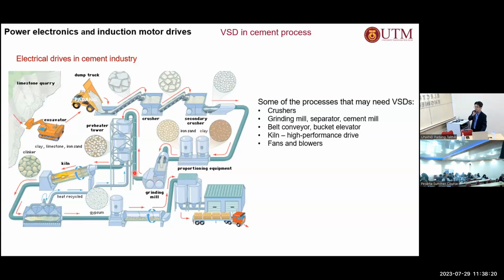And then of course, to transport everything from here, you have the conveyor belt, again using a drive. And if you use a belt conveyor, then you need to control the speed as well, because of the process flow, you probably require to reduce the flow rate. Then you probably need to control the speed of this belt conveyor as well. Now, and then it goes to the preheating process here before it is fed to the kiln, all right?